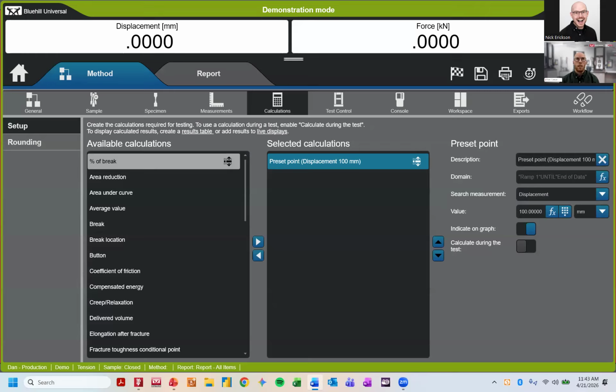And of course, your extensometer type, if you're measuring strain, whether a video extensometer versus a traditional clip-on, there's a lot of different influences at play, and they come with different advantages and disadvantages. So there's not really an answer to the question. I will follow up with this person to see if they have a specific question. But it can be overwhelming sometimes to look at all the different ways your setup can impact how much you trust the data coming out of the system.